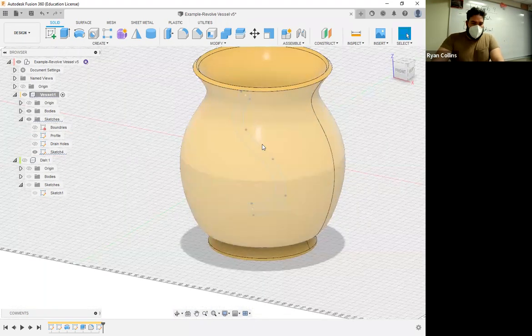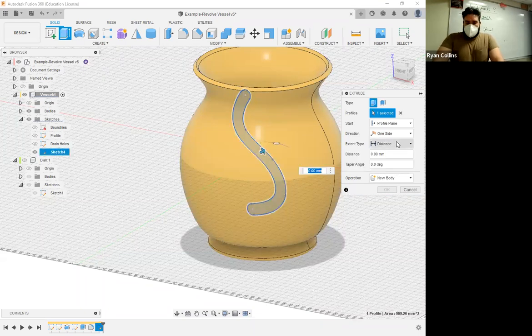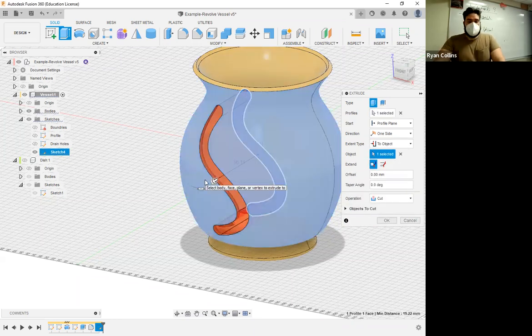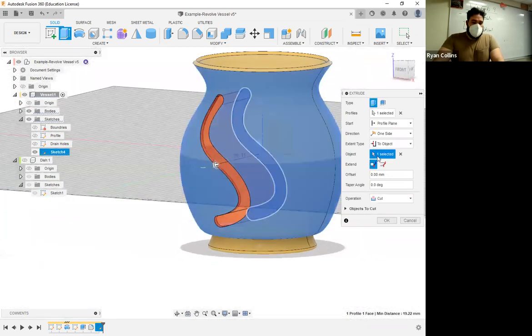Now you can see it's flat. It's much larger than the other things are. That's okay. I'm going to do the same, extrude, select that sketch. Let me see if it'll let me do a 2 object, because sometimes it won't let you use a 2 object on rounded surfaces. Oh, it did. Great. So that cut right through 2 object. So I'm still using this selection type. If I go back and change, it will recalculate always back to the surface. Great. It's uncut. That's what I want.